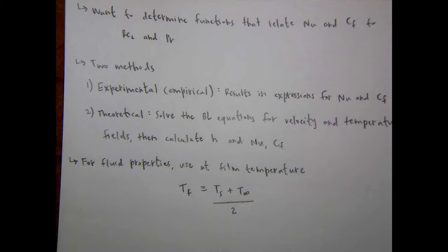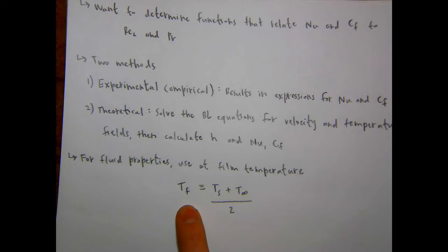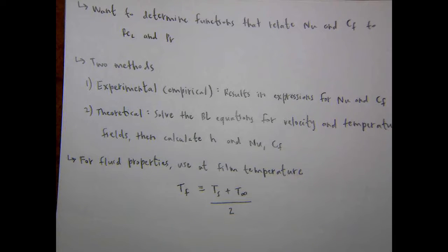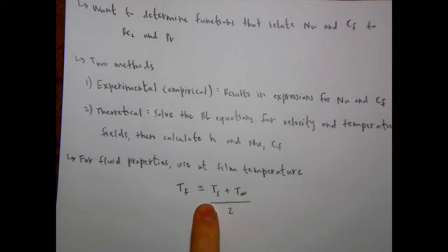So you calculate the surface temperature based on a guess of the film temperature, or just using the ambient temperature. Look up properties at that incorrect temperature, solve for the surface temperature, then you can calculate the film temperature and iterate until it converges. How do you know what your goal is? Basically when your answer stops changing, within like a degree or whatever you think is reasonable.